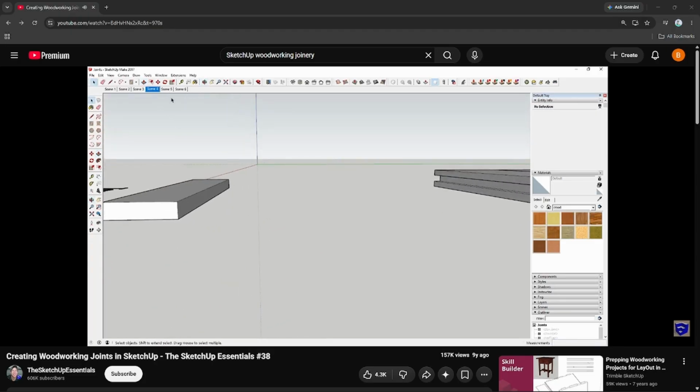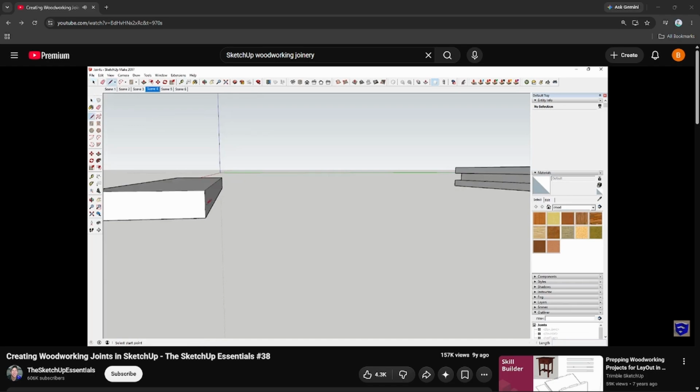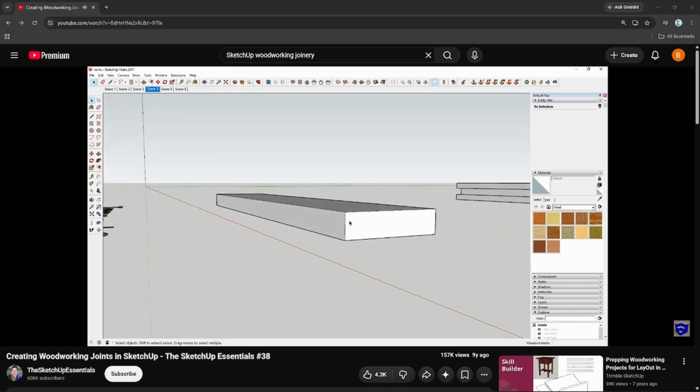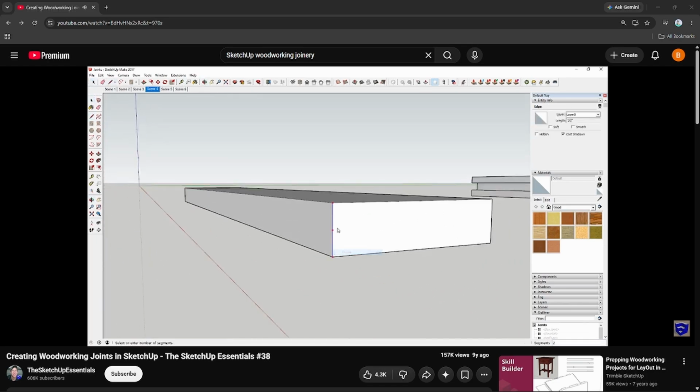What you could do is you could come in here and model it out. Basically what you could do on this face is divide this inline just like this. You could divide this into 3 segments, and what that would give you is a length just like this. And so what this would do is give us a little piece right here that's equally spaced with the pieces above and below that was 3/16 of an inch long.